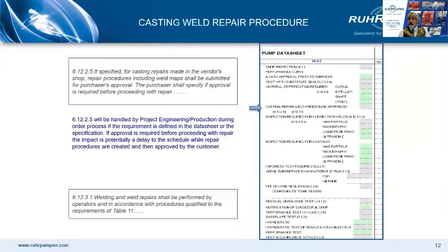Maybe you're machining the casting and you uncover a fault. Well, then that's a weld repair and is fully documented by the pump manufacturer. To save on time, the weld procedures are agreed in principle in advance, and a particular weld repair with its associated weld map is submitted for approval as and when required.